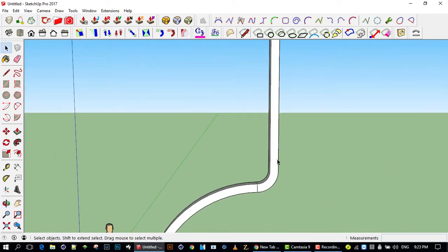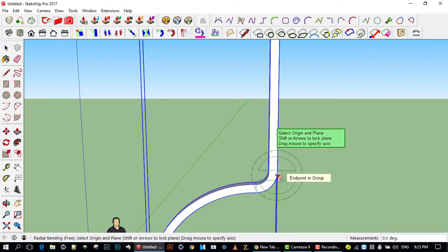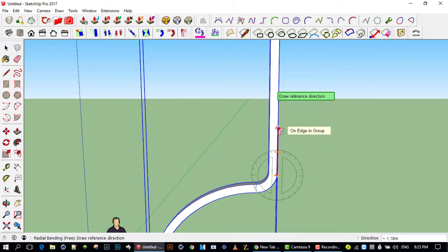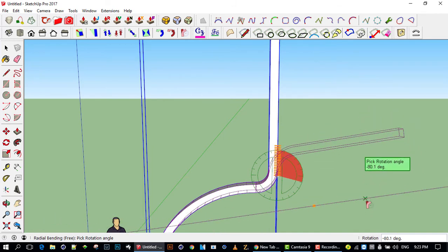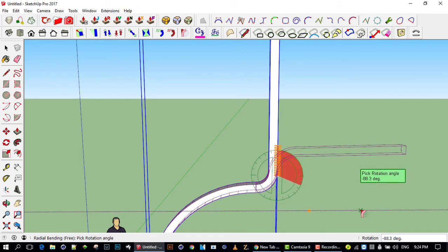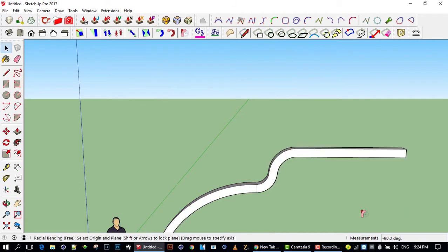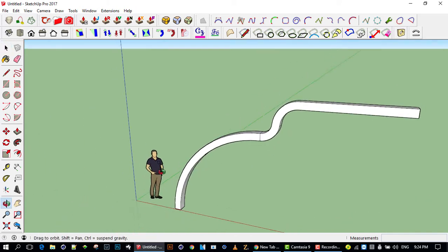And then I'm going to make this pipe go further to the right. Select the item, select it again, same thing, click on the area, just go a little up, click again, move in the direction, click, and then pull it down. Basically I let go of my mouse button, and when I move the mouse it's still going to navigate, and I'm looking at the direction. It's saying minus 88, so I'll choose minus 90, press enter, and there we go. And pretty much that's how you get to manipulate it.